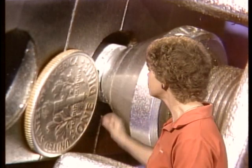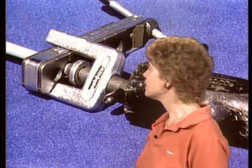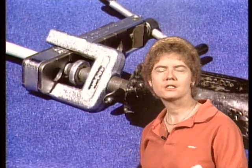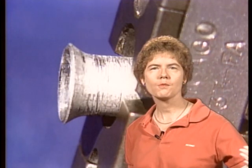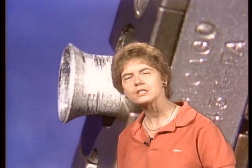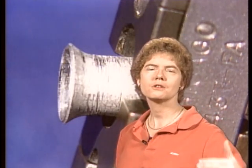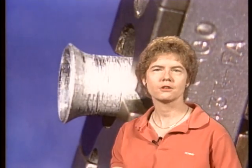The fourth thing that you do is project the end of the tube slightly from the top of the flaring tool. And how far out do you project it? About the thickness of a dime. The fifth thing you do is tighten the clamp bar securely to prevent any slippage. And the sixth thing you do is strike the plunger several times with a lightweight hammer or mallet and turn the plunger a half turn after each blow. And those are the 6 steps in order that the FAA wants you to be able to tell them on how to make a flare. And this is what it's going to look like when you get all done.